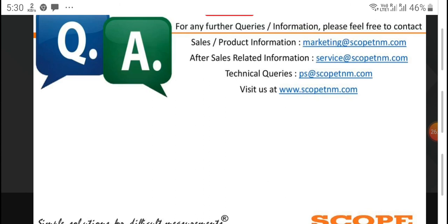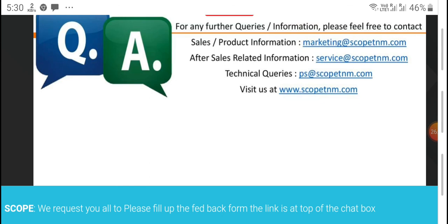Yeah. So the velocity of propagation is the major thing we need to calibrate for getting the exact fault location, and the total length of the line should be known in the best possible way. So by using these two pieces of helpful information, we can get the most accurate, or calibrated, result. Exactly.